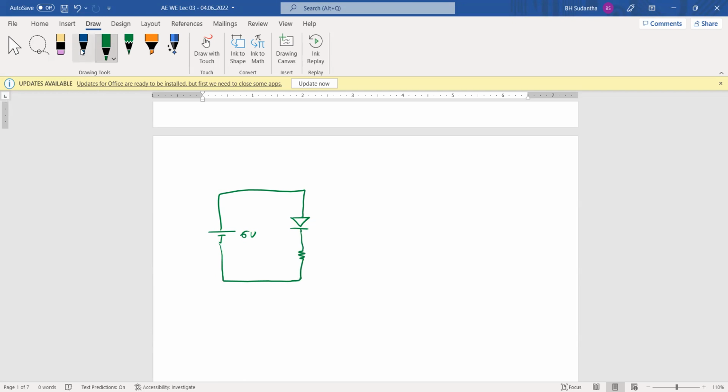Normally the LED forward voltage, we can take generally as 2.2 volts. And when you turn it on, the LED can have 5 to 30 milliampere current going through it. Depending on the pass-through current, the LED light intensity will be determined. Generally, we can take 10 milliampere as very much enough. And if you consider 10 milliampere going through this LED, then this is R.